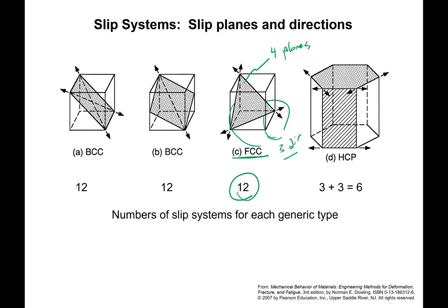All right. Now, if we take a look at the hexagonal close pack system, remember that for the face-centered cubic, we did this ABC packing, and for the hexagonal close pack, we did AB packing. But the atomic packing factors for these were both 0.74, so they're very similar structures in terms of their density and their packing efficiency. But we messed the symmetry up when we changed and went to this AB. We no longer have cubic, but we've got hexagonal.